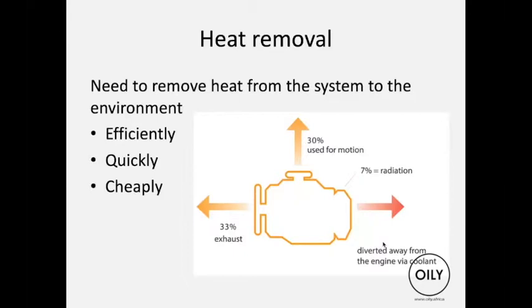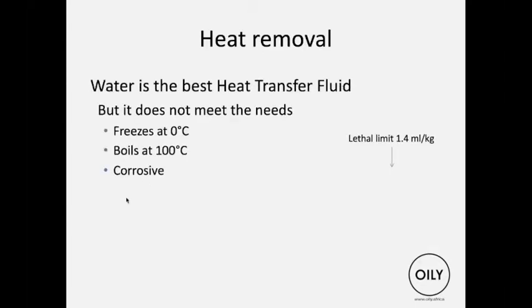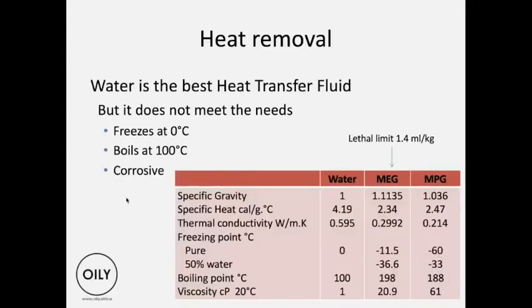So the cooling system has so much heat coming to it from the engine and has to dissipate that heat to the environment very efficiently, quickly. Water is the best heat transfer fluid. The specific heat of water is by far the best, but it doesn't meet the needs because it freezes at 0, boils at 100, and is corrosive.